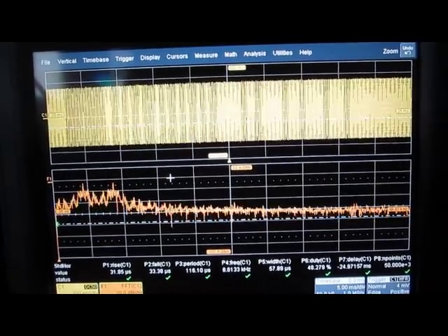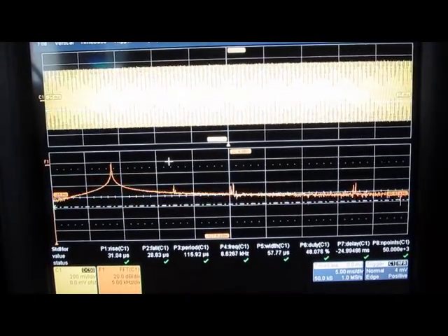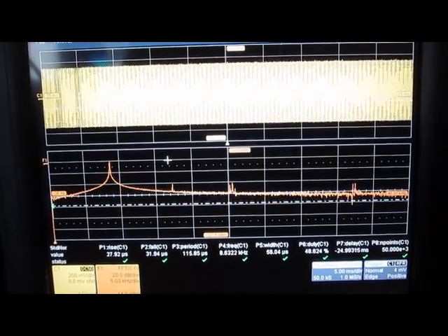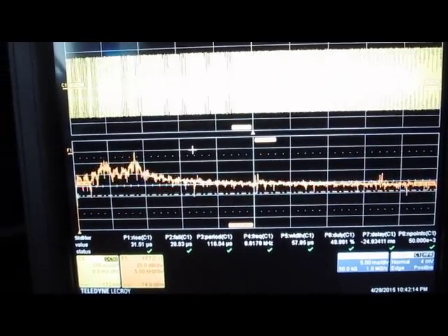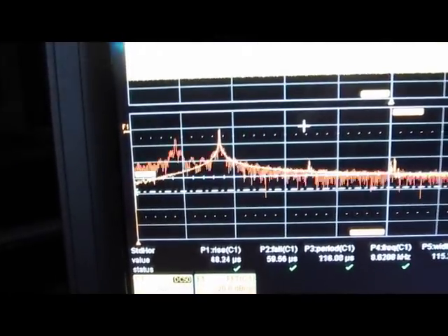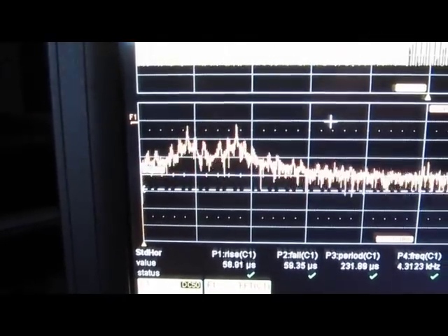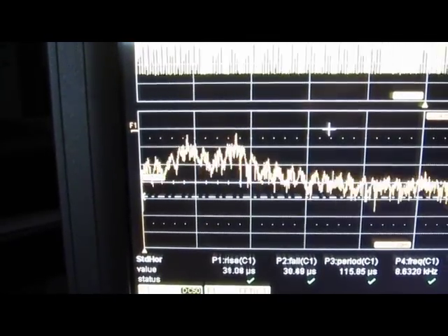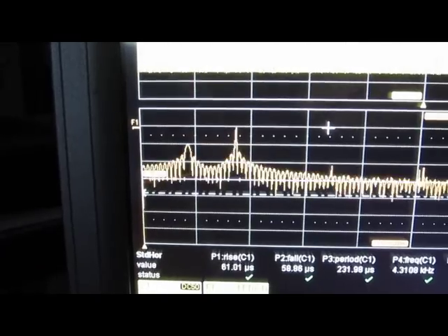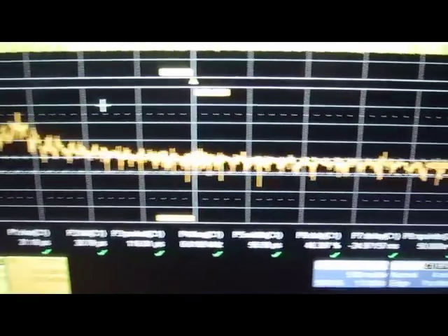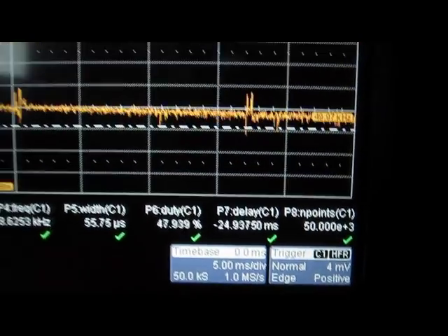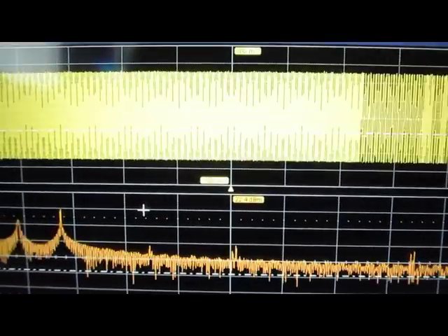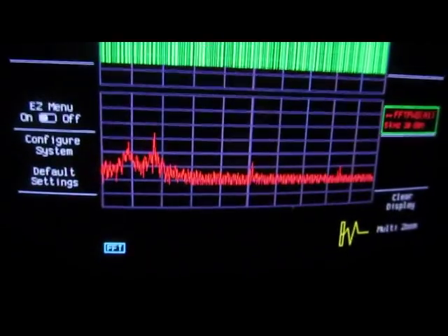See, the ARB is now outputting an FSK signal. You can see the display getting updated as the data comes through. You can see the carrier to the right. Shift on the left. Again, we're looking at 5 milliseconds per division. This goes pretty quick here, really. Let's compare that with the 7200.